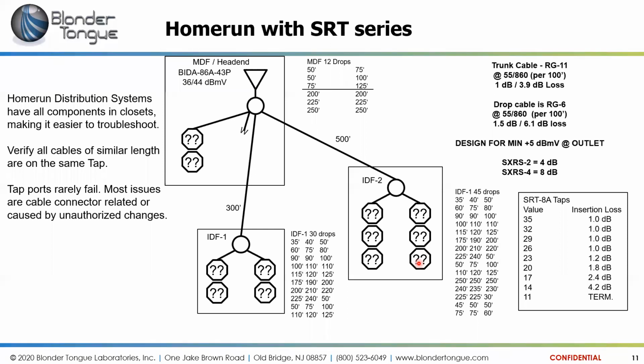Hi, Don. Experience. Common cause of suckouts I found to be a directional coupler installed backwards in the trunk. That is very possible. Very devious problem to find, but good idea to check that the in and out ports are correctly oriented on the trunk. That is absolutely true.